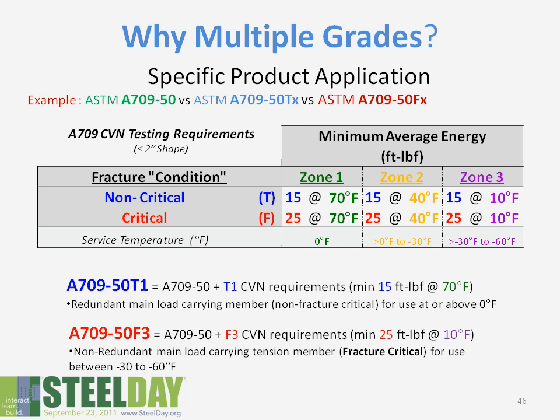some Charpy requirements. For non-fracture critical, we require a minimum impact energy of 15 foot-pounds. For fracture critical, a minimum impact energy of 25 foot-pounds. And then depending upon where this is going to see application, we have a service temperature zone. We will change the testing temperature.